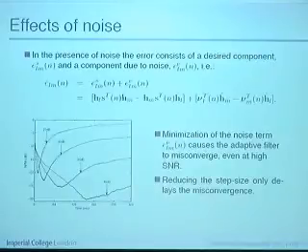And trying to minimize these 2 components together kind of messes things up a bit. You can see here an example of what happens. The adaptive filters start to have this strange behavior where they start getting down, converge towards the right solution, and then they misconverge into something else.